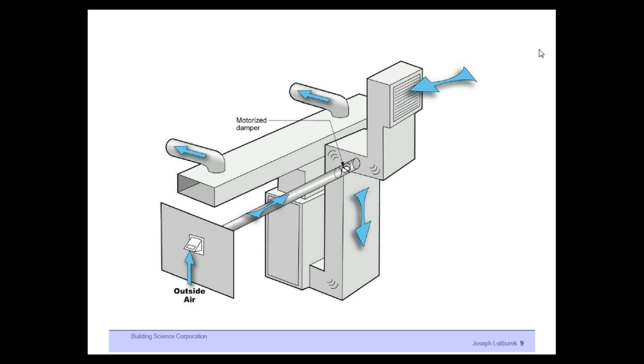So you in essence have, say, 2 bathroom fans operating each at 25 CFM continuous, coupled with outside air being brought in at 50 CFM, and you have a fully balanced system. This is not as elegant as a balanced HRV or ERV, but it certainly works.